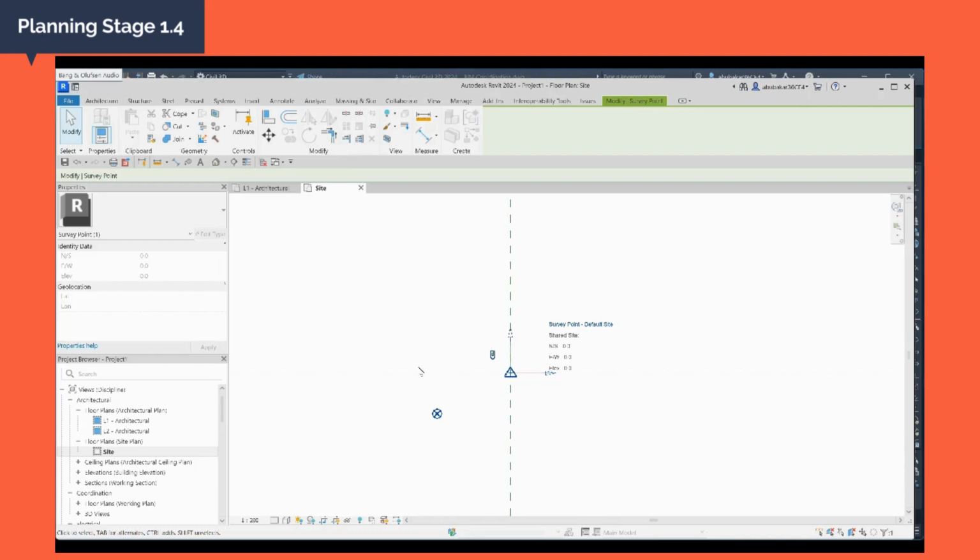You want to do site coordination irrespective of whether you are working entirely on a building or different units of building, because this information will be a link file to the site. So you can work in millimeters at your various individual building designs, but the link file will be coordinated in the metric space of the site, which will be in meters.